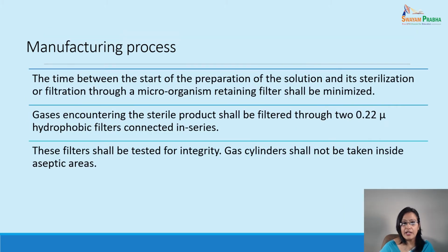Next, the time between the start of preparation of the solution and its sterilization or filtration through a microorganism retaining filter shall be minimized. This is very important. We are sterilizing the equipment and validating the process and everything, and if we start the manufacturing process after a long gap, this will not work actually.